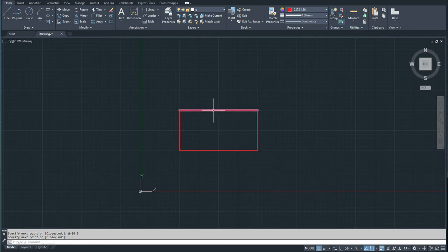So the orange one, it is the relative coordinate system using the at. And the previous one, undo. The yellow one, it is the absolute. If you remember, we chose the absolute coordinate system. So, guys, we learned together how we can draw the line using the ortho mode, which restricts the movement in the vertical and horizontal direction. In this case, just start point and then move the mouse and type the length, that's it.